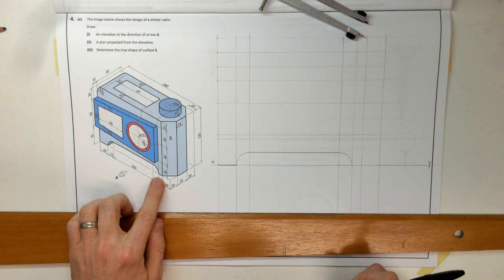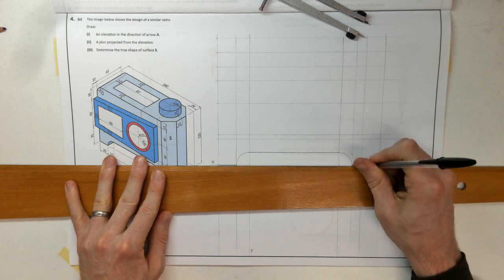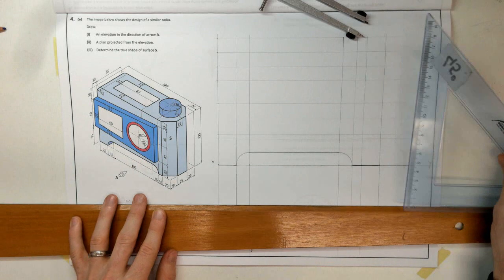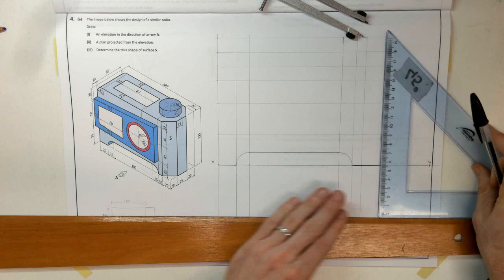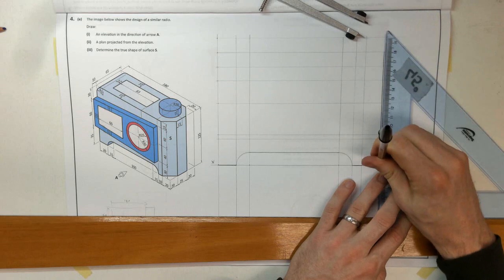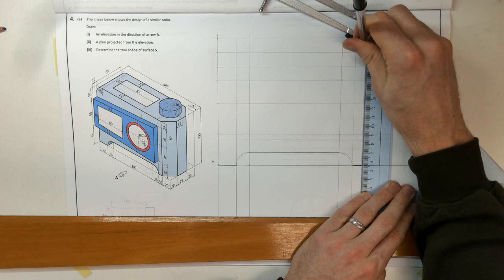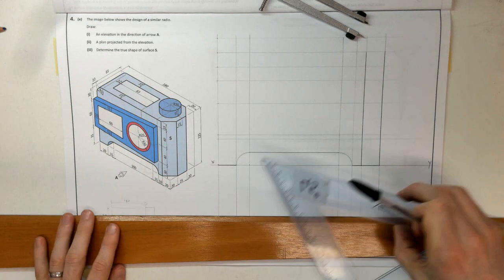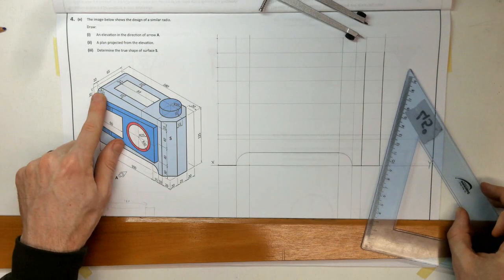Now we're going to have 10 and 20, so there's going to be a heavy line to the end. Now we're going up to my 125, yeah, that'll be a heavy edge. So this is my surface S, and in there we're going to have the heavy edge running along, and then a radius 15.